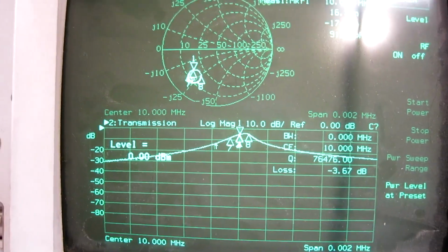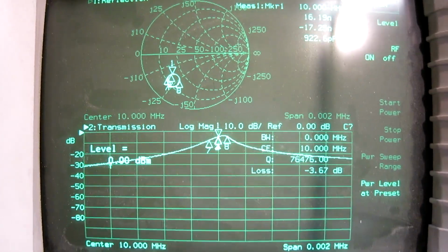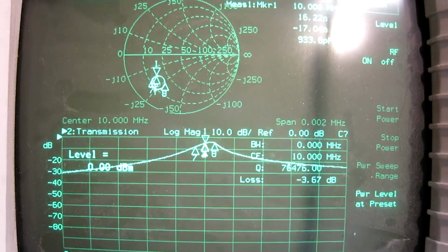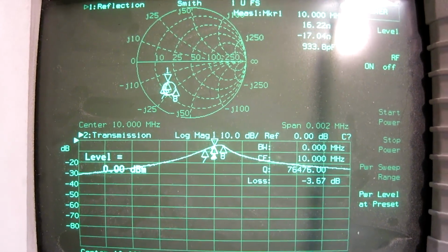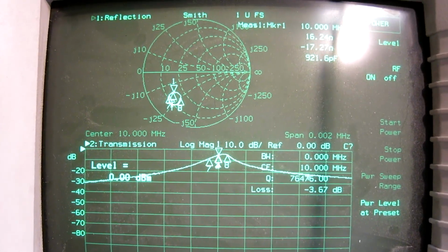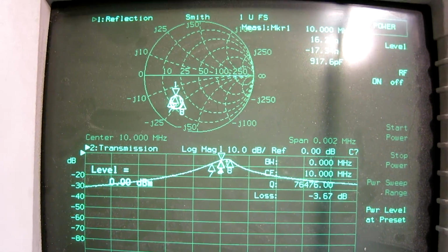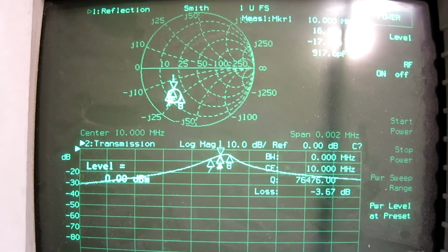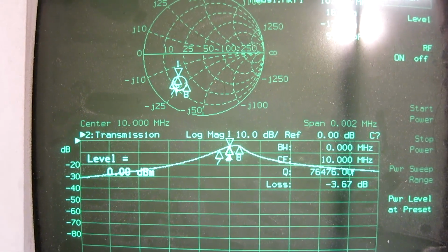Conclusion: crystals in parallel allows a higher signal level, higher by the number of crystals. So this directly improves the signal, because the thermal noise on the crystals is going to be lower because of the lower impedance on the resonance.